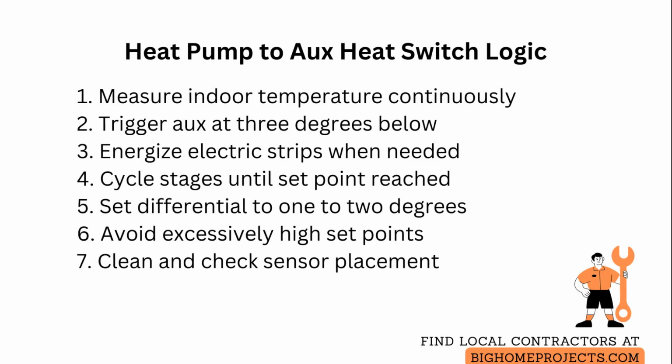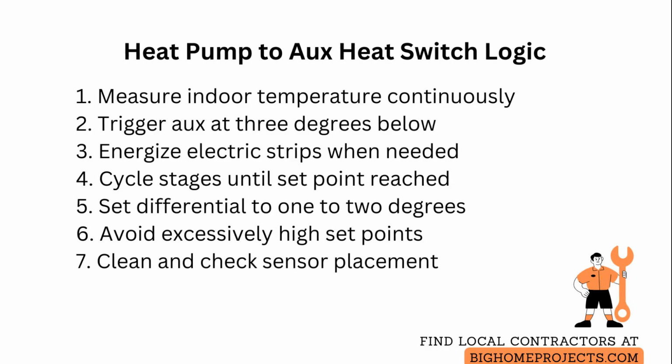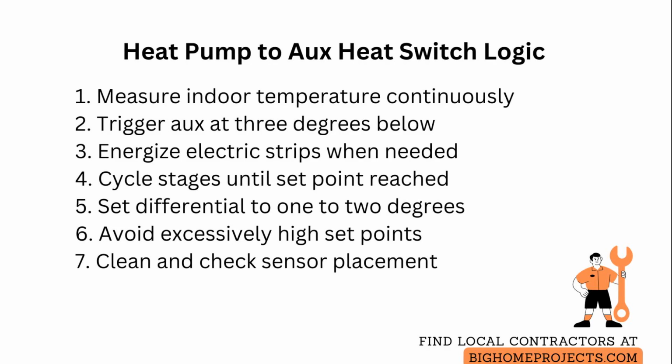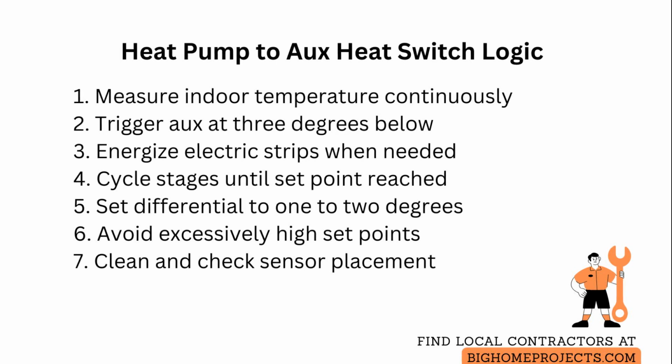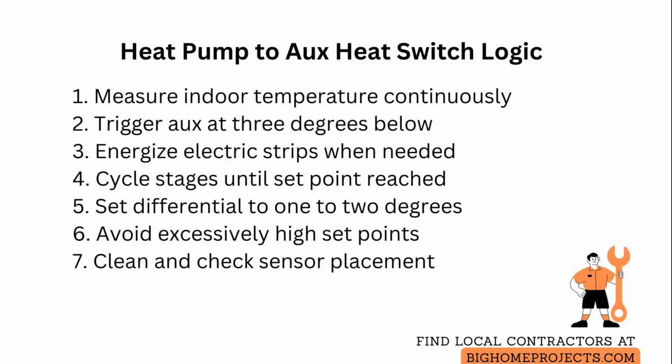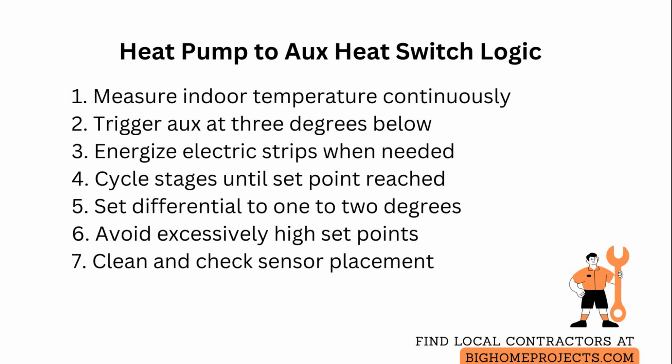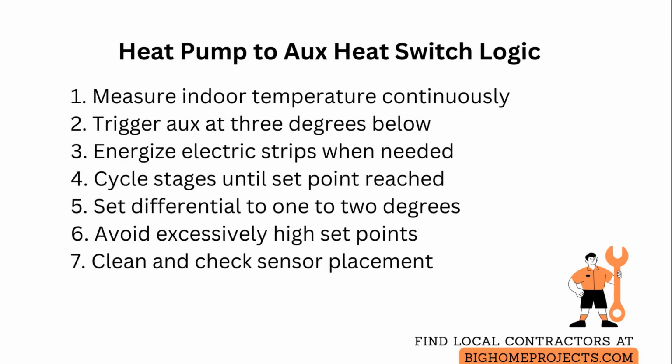Because this model does not use an outdoor temperature sensor, the logic focuses entirely on indoor performance, which simplifies setup but means outdoor conditions are not directly factored into the switch decision. To tune comfort and efficiency, set the thermostat differential no wider than 1 to 2 degrees for responsive control, and avoid setting the set point excessively high, which forces more auxiliary use. Regularly clean and check your heat pump and thermostat sensor placement so the indoor reading reflects true living space conditions rather than a drafty hallway or direct sunlight.